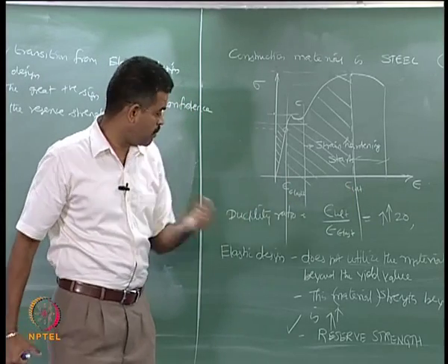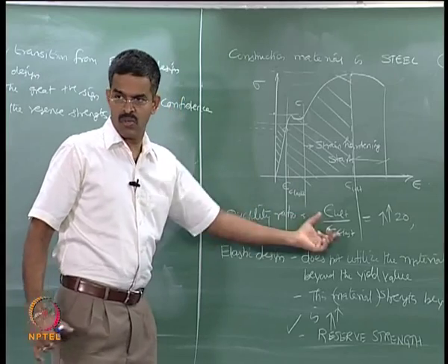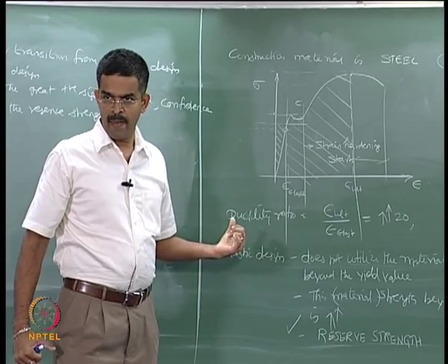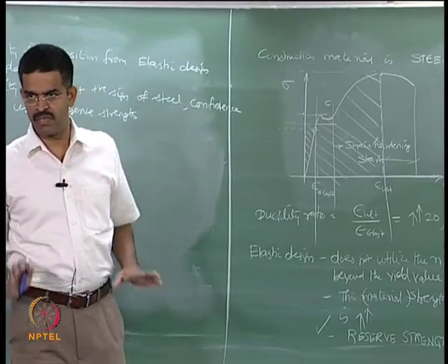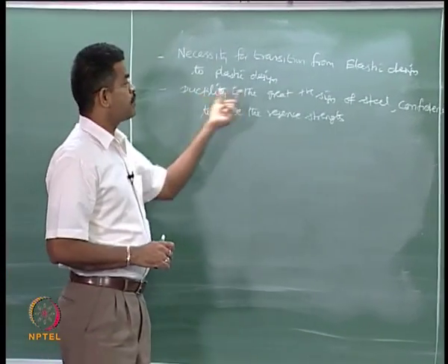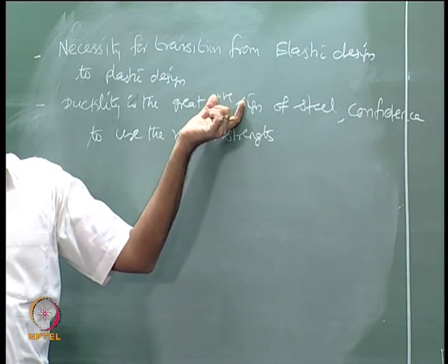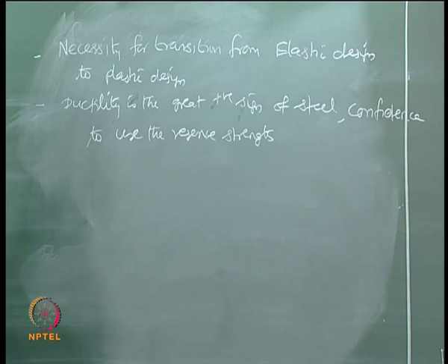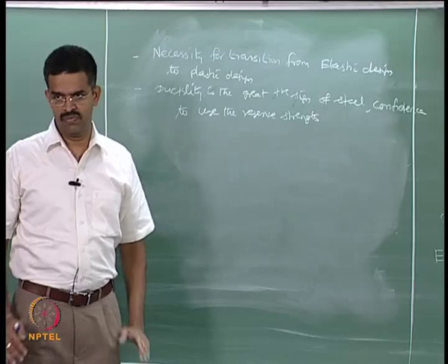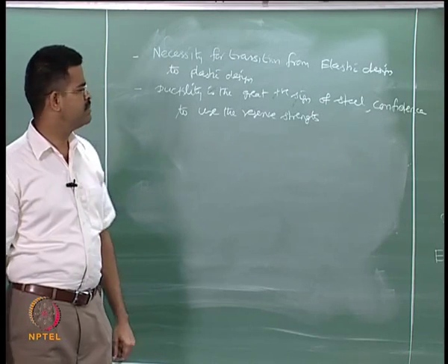That multiplier is what I have called the ductility ratio. That guarantee was seen in the material behavior as far as steel is concerned by the designers. That was the positive sign which designers felt: yes, I can stretch the material beyond the elastic limit or beyond my first yield value. Okay.